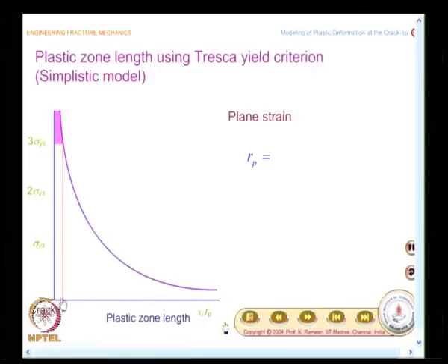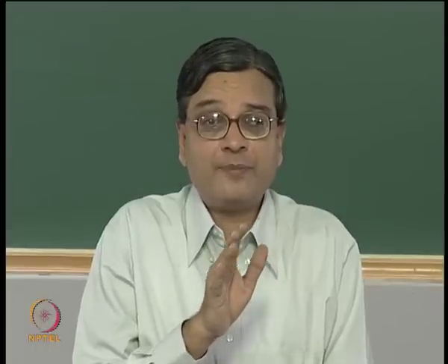First we have said we would simply find out the yield strength value, based on that find out what is the length, based on this find out what happens as a function of theta. That would give the plastic zone shape, which is very approximate, because we are not considering redistribution of load, we are simply plugging in mathematically whichever are the points which reach the yield strength value.